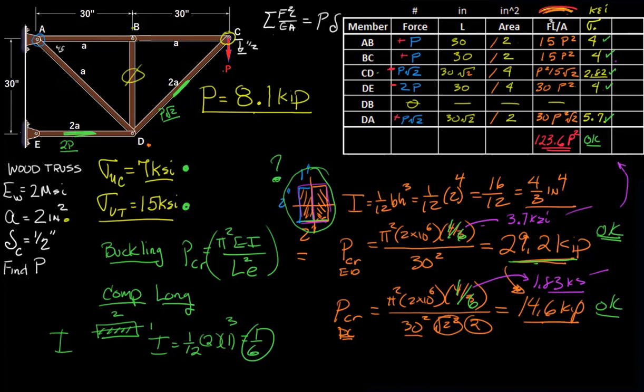In this case, though, our truss is okay. It will withstand the compressive and tensile stresses, and it will withstand the buckling loads that are being applied to it. So the strain energy methods are extremely useful. We can use them for calculating impact events with different types of beams or structures by converting to the Hooke's law equivalent, or they're extremely handy in the case of compound structures like trusses.